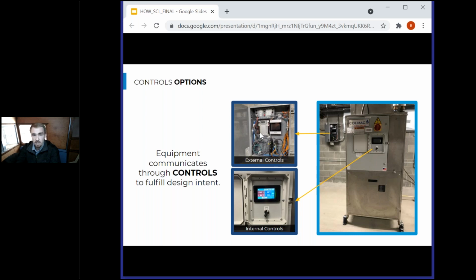And the second, more robust seeming option is the controller just monitors the heat pump. It controls a lot of other things in the building, but the external controller just monitors the heat pumps. And the heat pumps just tell them, okay, I'm running now, I'm making these temperatures, and then the heat pumps are just looking at the tank temperatures and running on their own. And that will allow less conflict between the controls contractor's idea of how the heat pump systems work and the manufacturer's really special oddities built in to the heat pump electronics themselves.